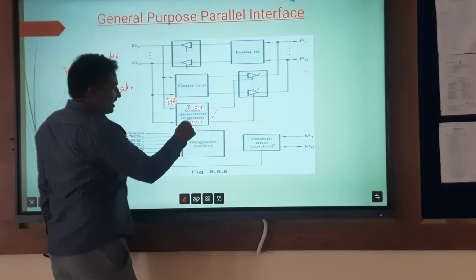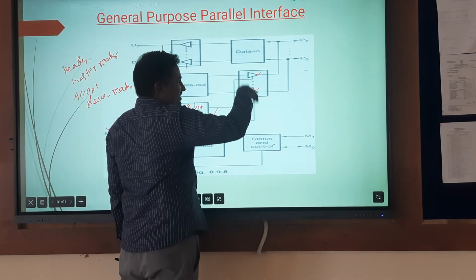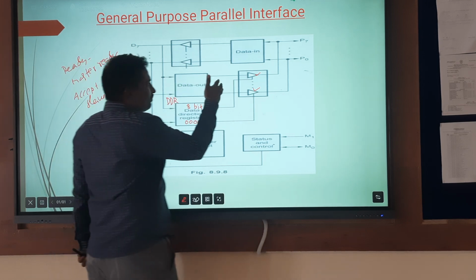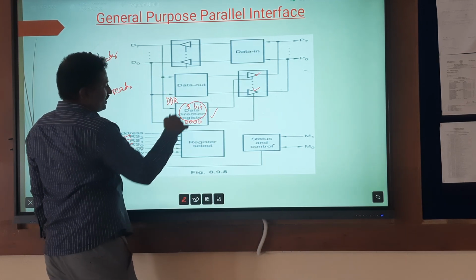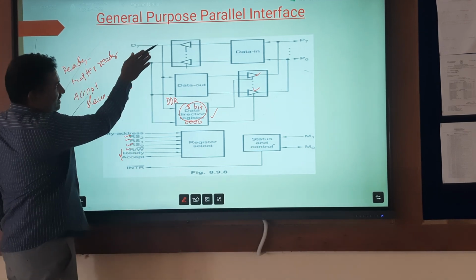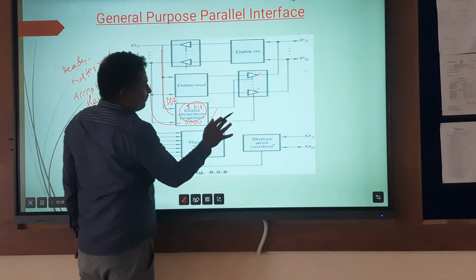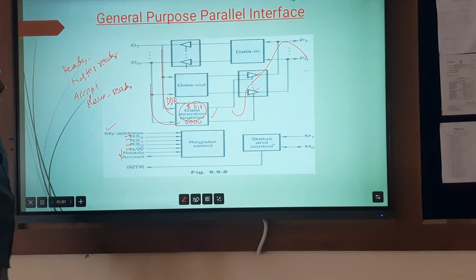If all the bits are equal to 1, then all the drivers or tri-state buffers are activated so that the data in the data out register will be transferred out. Okay now. The inputs to the data direction register are applied from the data lines. With this, it can be identified whether the data will be transferred or not.